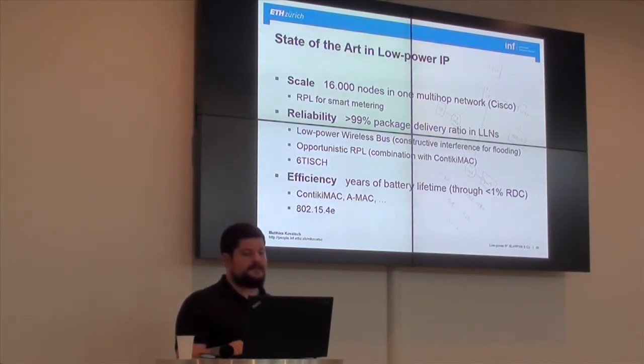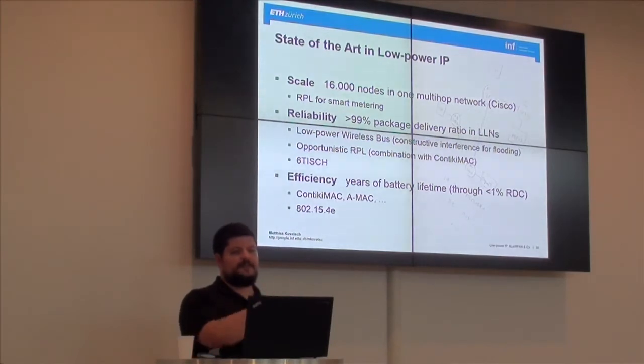And then the last thing is the 6TiSCH working group in the IETF, which is basically about time scheduling and channel hopping. So you do not only use one channel, but you hop around the channels a bit like Bluetooth, if you know how that works, to mitigate narrowband interference. And time scheduling helps because you can assign specific slots to a node. If this node has to send a lot of data, it receives more slots. And that's why it gets more reliable.